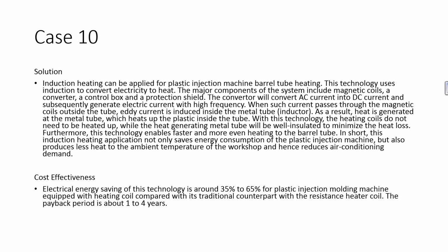Furthermore, this technology enables faster and more even heating of the barrel tube. In short, this induction heating applies not only saving energy consumption of plastic injection machine, but also produces less heat to the ambient temperature of the workshop and hence reduces air conditioning demands.